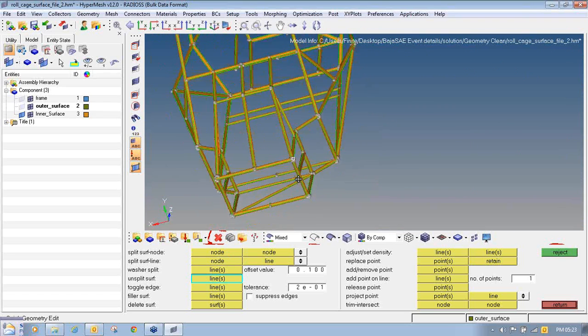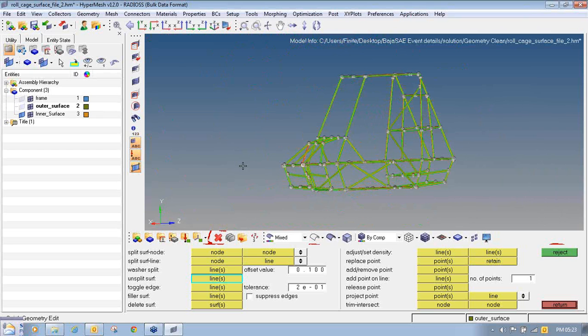So once you have done that for the complete geometry, it will take around 1 day to edit the complete geometry perfectly for both inner and outer surfaces. So within a day it will easily get completed, so it will not take a lot of time. It's a very simple process to edit the geometry in HyperMesh. So you can simply edit these geometries and convert it into a perfect enclosed volume, so that the time for meshing and quality of the elements will improve drastically.